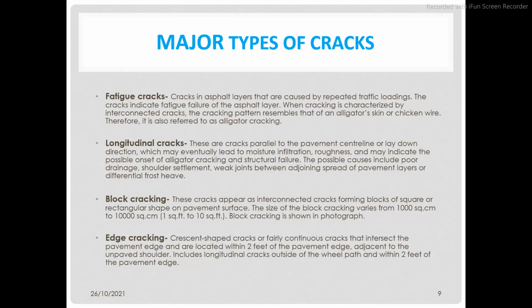The first one is the fatigue crack. Fatigue crack is commonly called alligator cracking. This is a series of interconnected cracks creating small, irregular shaped pieces of pavement. It is caused by failure of the surface layer or base due to repeated traffic loading.